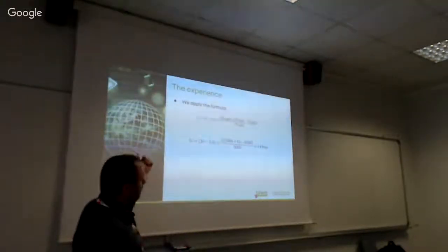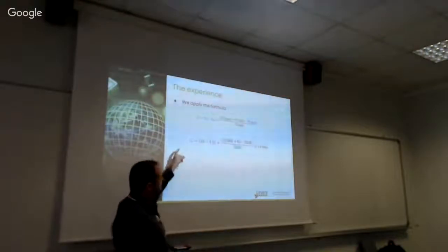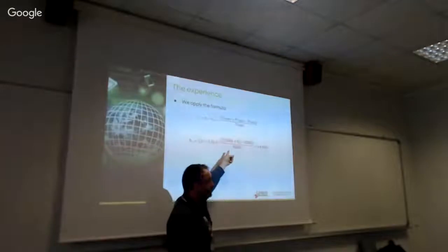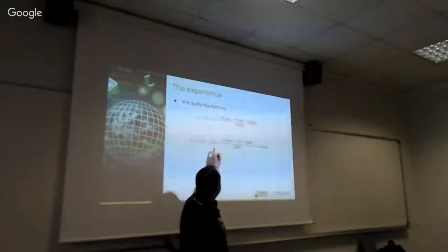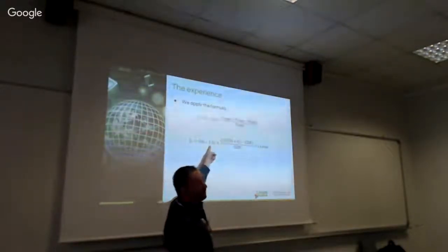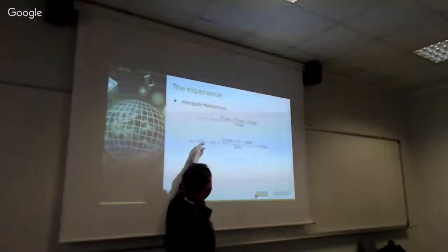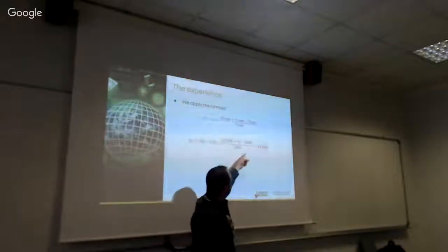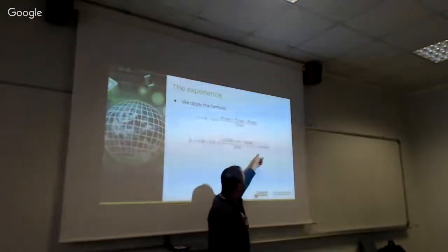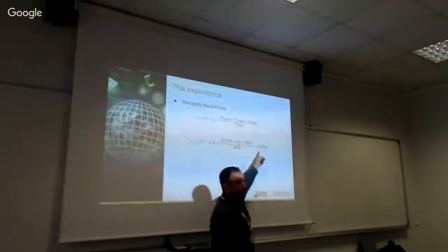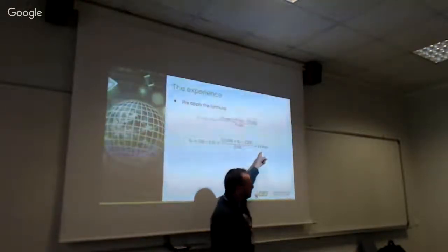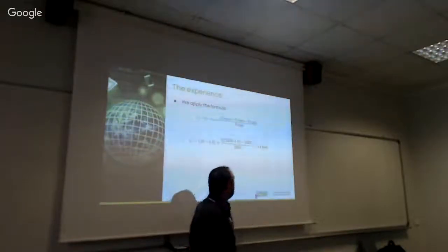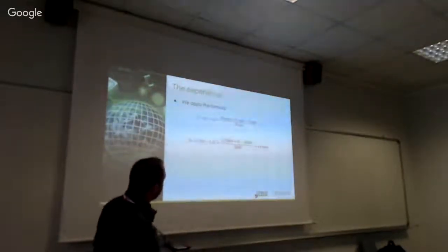So with the formula we had, to reach this targeted power, we remove 1.5, the wake-up latency for this idle state. That's the idle duration, that's the maximum power, the targeted power. And that's the period we compute.